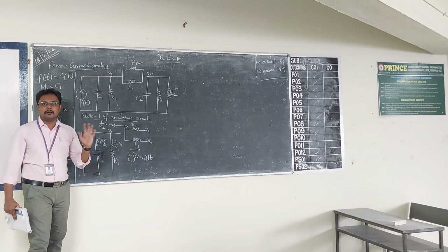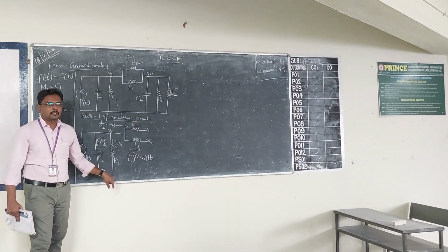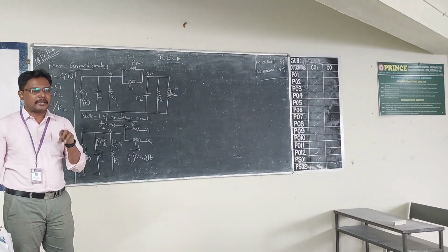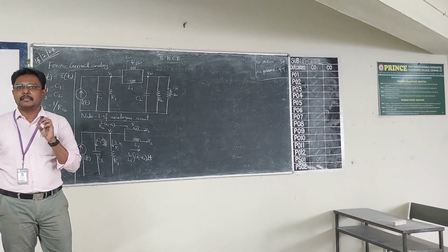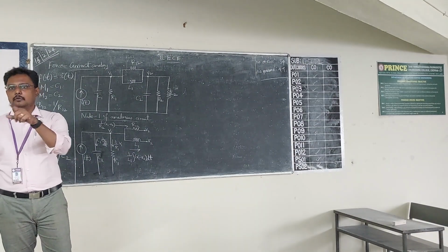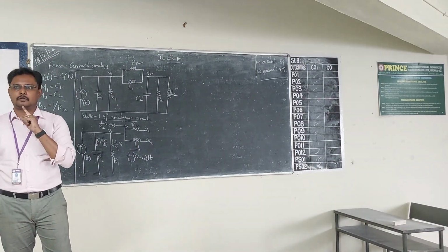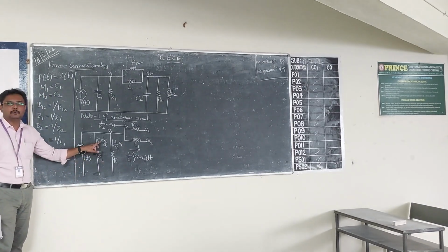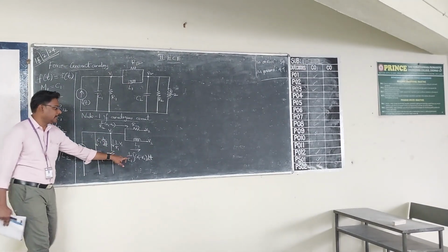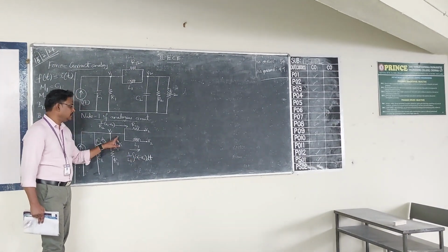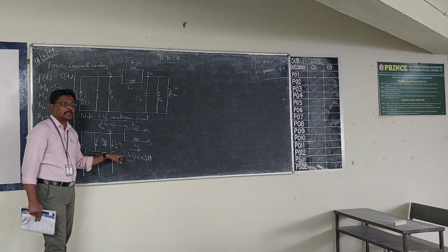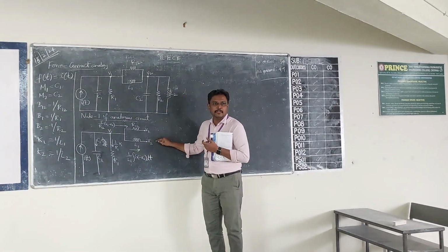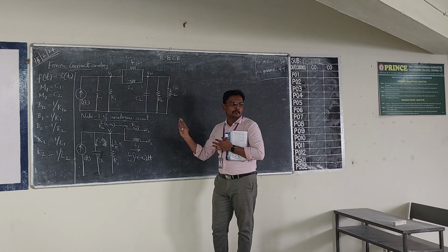That is why we separate and draw the diagram. So you are going to write the value of the corresponding electrical element according to the tabular column we saw in the first class, on the formula. C is C into dV by dt. L is 1 by L integration of V dt. R is V by R, V1 by R. Understood? So here I have put a dot. V2 belongs to the second node.